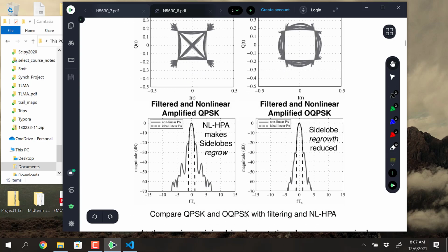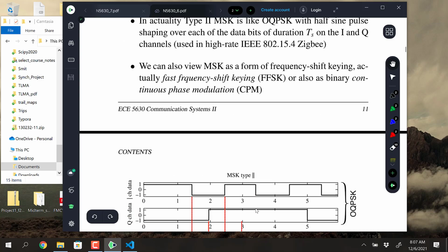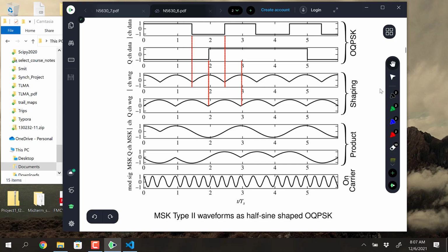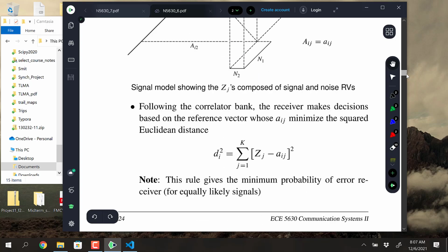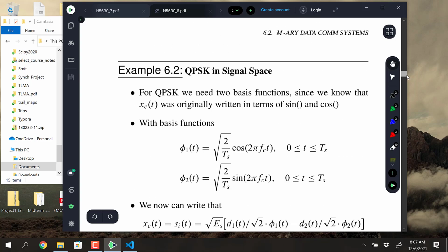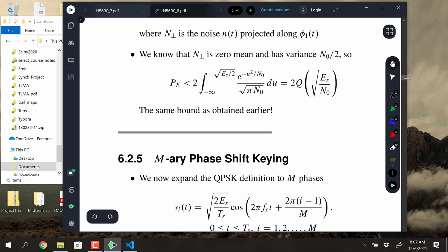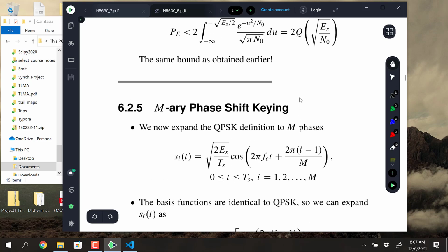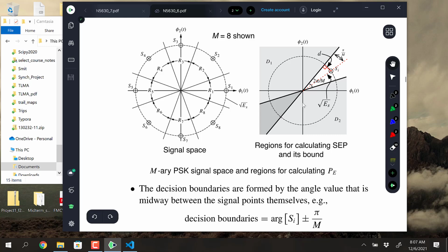But when you go through the serial portion, and I'm not sure I actually have the best picture in here. I guess I probably don't, but it seems like there was a summary over here. Wasn't that the discussion where you had to divide by log 2M, right? Yeah, but we're not looking at symbol error probability in the end. We're looking at bit error probability. So it turns out that this was a bound, but if we were to go in and look inside, I'll just pick a constellation for MPSK, and we look at it in terms of energy per bit, not energy per symbol.